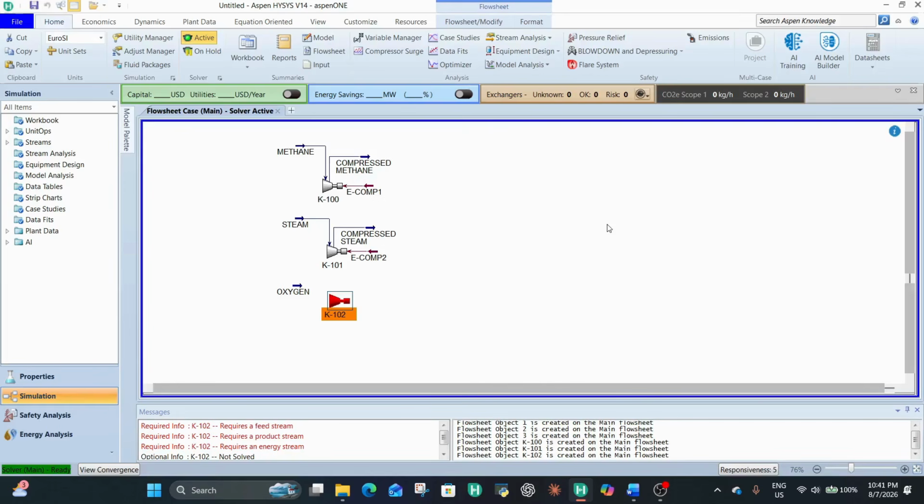So basically, to avoid the stress and complications in processing, an air separation unit is needed, or you could just get supplied an oxygen pure stream, basically pure oxygen for the process. So that's the reason we are using pure oxygen.